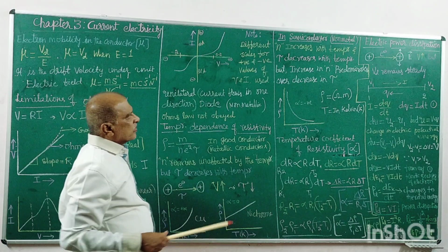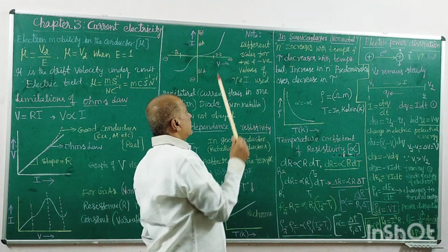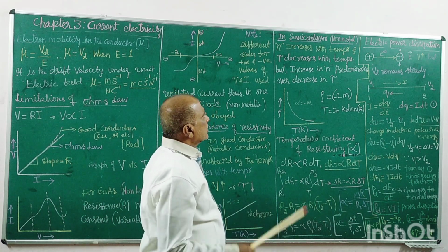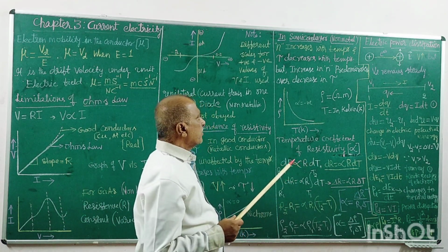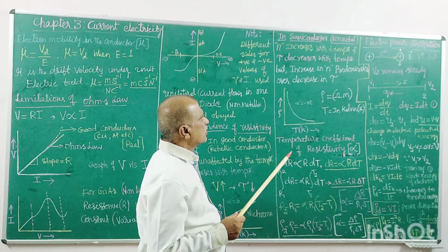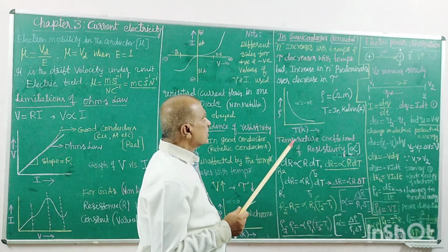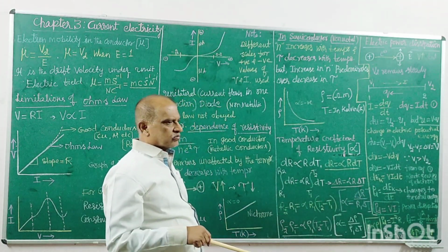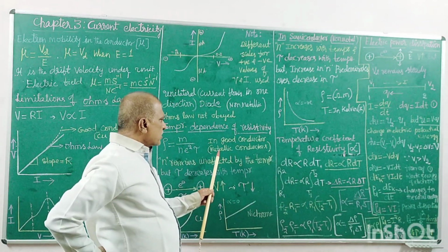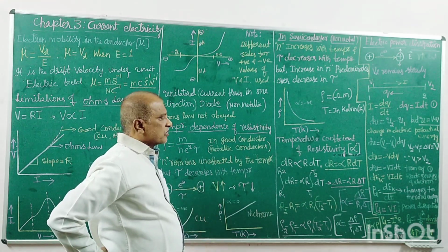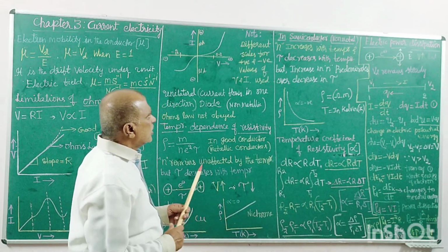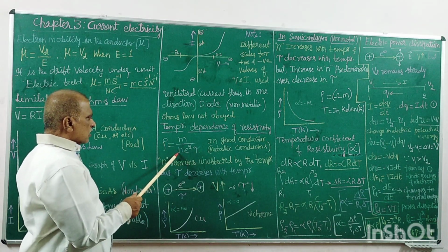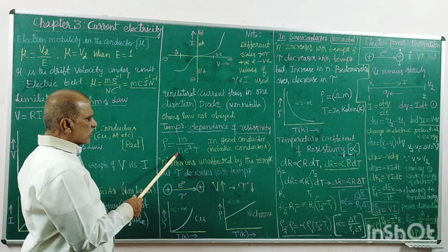Let us take another material, non-metallic, or a semiconductor. A semiconductor is either silicon or germanium. What is the difference from the metal? The difference is that these atoms are ionizable with the effect of temperature, whereas metal atoms are not. In the case of a semiconductor, the same equation for resistivity applies, where n is the number of free electrons.